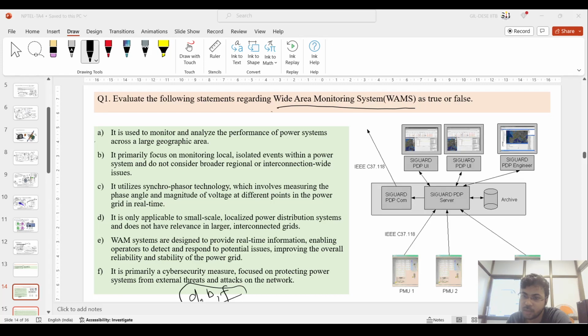And DOD will affect SOH. Yes, I have said that SOC will affect SOH. SOC is the same; you can define DOD as 1 minus SOC. It will also affect the depth of discharge because you have a certain limit that you should not discharge below 20%. You should not overcharge. Also, there will be certain limits. And if you see the lead acid battery which you have at home also, you should not discharge below 50% SOC level. That also impacts the life of that lead acid battery which you have at home.